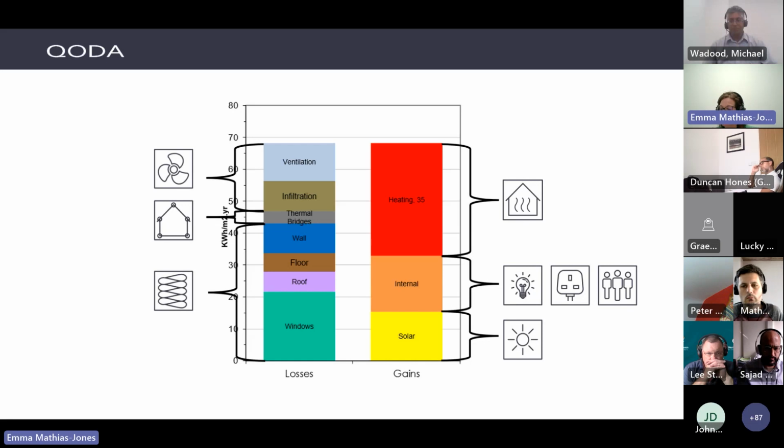If we were looking to lower that heating demand, we could look at improving the U values, which is fairly straightforward: you add more insulation. We could make the building more airtight, to reduce infiltration, and we could also use a system like mechanical ventilation with heat recovery. But as we reduce the U values, the thermal bridging gets even more important. So that's something we also need to address, and this is the bit that's becoming ever more important.